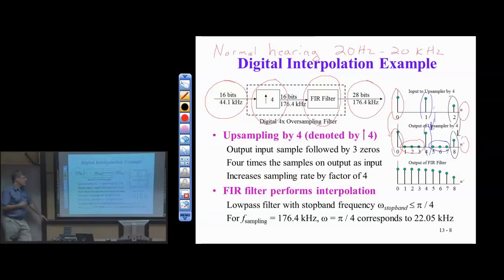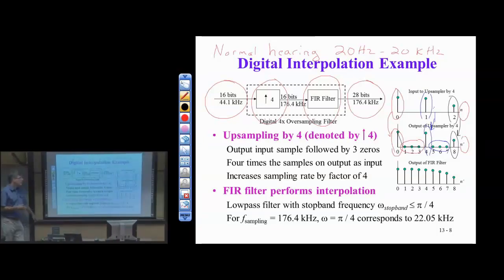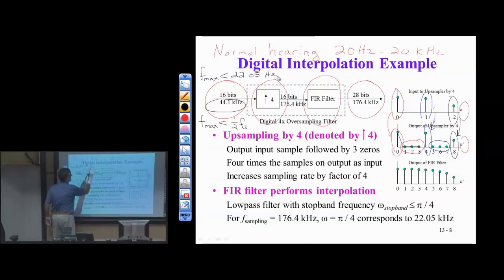But it's a distortion. We can remove a lot of these artifacts, certainly any that are at frequencies beyond a value we didn't have to begin with, simply by filtering and nothing more. So if we look at what we had before, our initial sampling rate is 44.1 kilohertz, which means that our maximum frequency possible has to be less than half the sampling rate. So the maximum frequency present in this original signal that we're starting with is frequencies less than 22.05 kilohertz. Let me fix the units there.